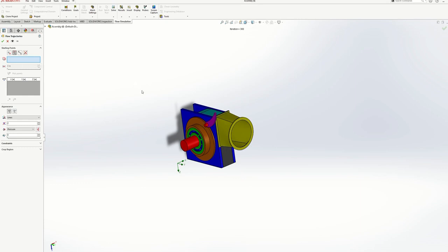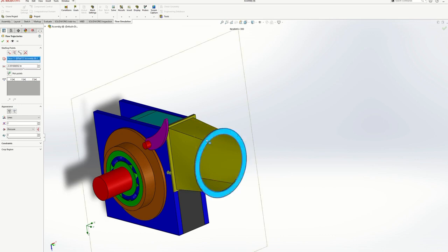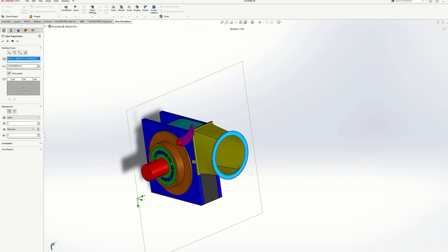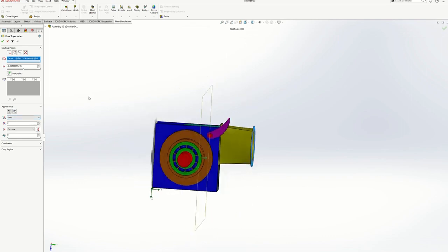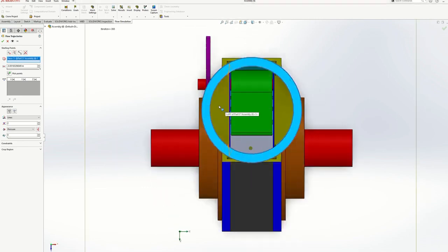Then select the phase to be this phase. Then make sure that the arrow is to the highest point towards the face. Press spacebar and choose top plane. Here it is. Click on Pick Points from here, and I'll select